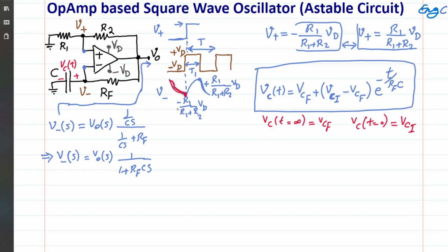I mean, I can do the other way. I'm just trying to make it as simple as possible. So imagine we are at the most negative voltage for the cap, and we are charging up to get to the most positive voltage for the cap before the oscillation behavior changes again. But we know that if this oscillation behavior wasn't happening, the cap would have charged up to the V out voltage, which is plus VD.